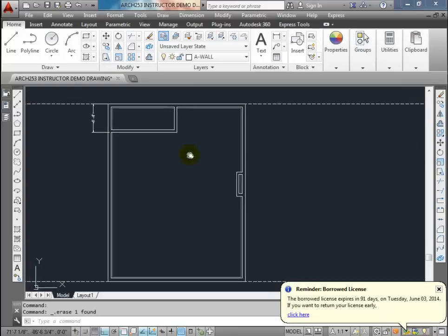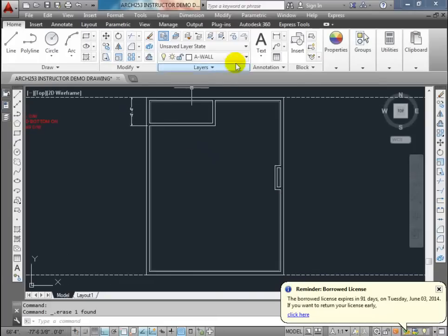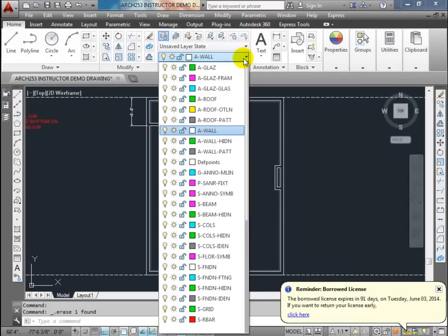We're now going to look at openings. So we're going to actually now draw our openings. So you remember back to the lecture when we did our windows. I'll draw a window symbol here first so we can get that window out of the way. And the window symbols are actually going to be using, the frame is going to be a glaze frame. So this is going to be the frame. Then we're going to have the sash. And the sash will also be a glaze frame. And then the glass is going to be a glaze glass. So that's the layer we're going to use for that.